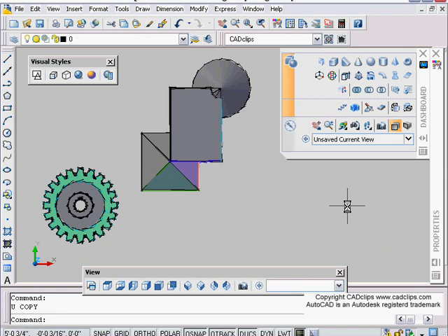Hello and welcome to another CAD clip on AutoCAD 2007 3D, and we're going to talk about the slice command, similar to our section plane command that we did in an earlier lesson. Section plane is different in that it retains the part that's being sectioned off, and if you erase the section plane, the removed part that is being sectioned away comes back. So slicing really slices it in half into two parts, and you can retain one or the other.